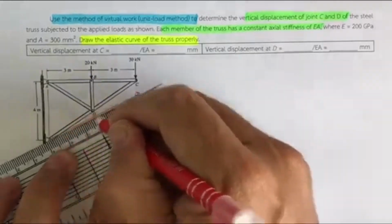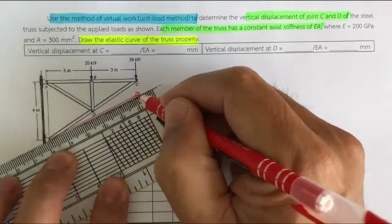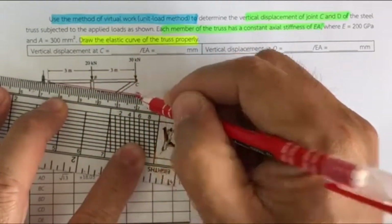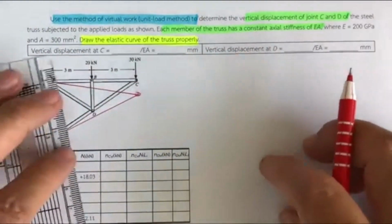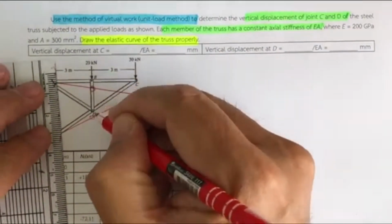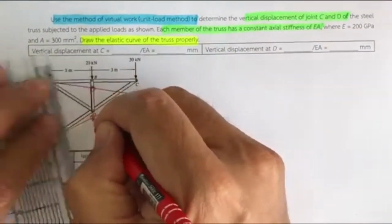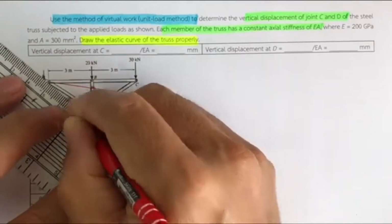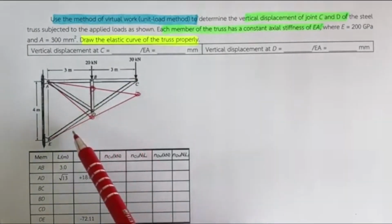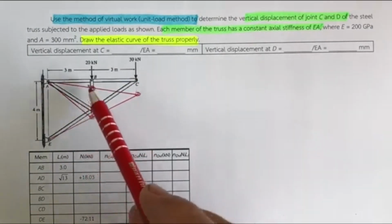So this portion of the truss will deform like this, and then B should be here, D supposed to be here, and AD will have this. And then you can see some of the members going to be in compression, for example this one and this one, and some going to be in tension.